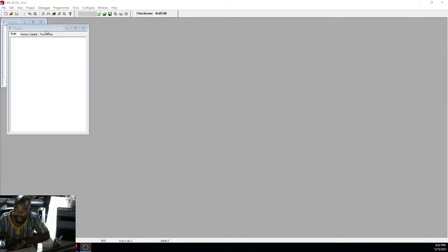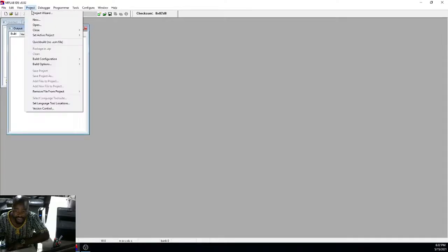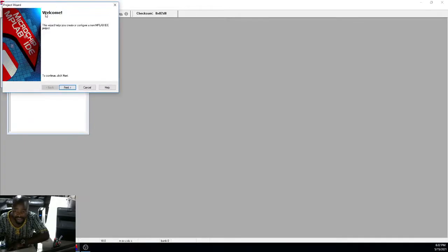On this video, I'm going to show you how to create a project using MPLAB version 8.92, an older version of MPLAB. Let's get started directly. To create a project, you basically go to project and then you select project wizard.